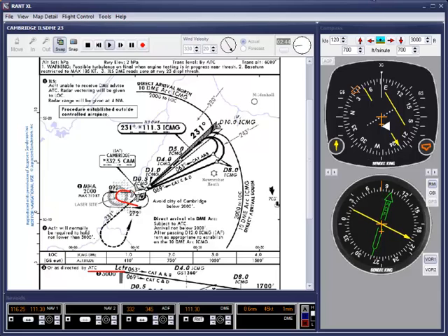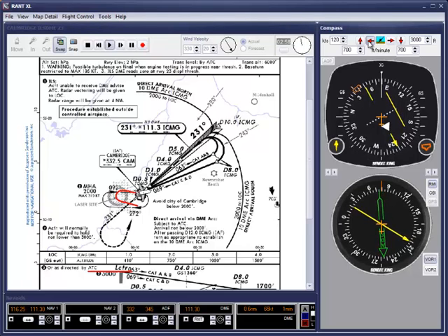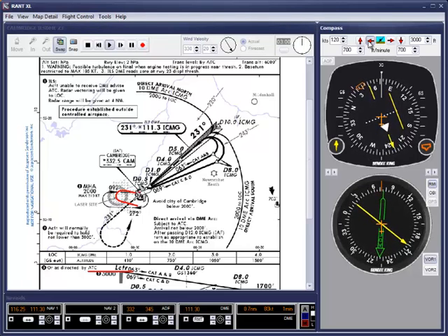On the way in, I make any necessary adjustments to maintain this track in the hold, and I know that the needle will drop approximately on the whole minute. There goes the needle. Turn onto the preset heading and wait. Make a radio call if required.